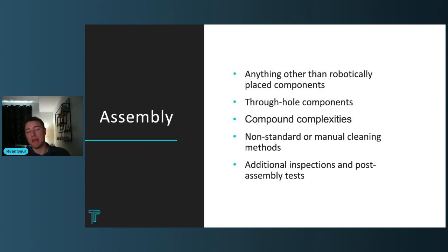And if you're building in mass production, actually that's a relatively low additional unit cost associated with that. But in prototyping, this can be a very dramatic element of your cost for fixturing. And I would say that goes for SMT and through hole as well. If you can avoid fixturing, you're cutting thousands of dollars off of your SMT and through hole pricing. So that can be huge. It's sort of a theme, I would even say.